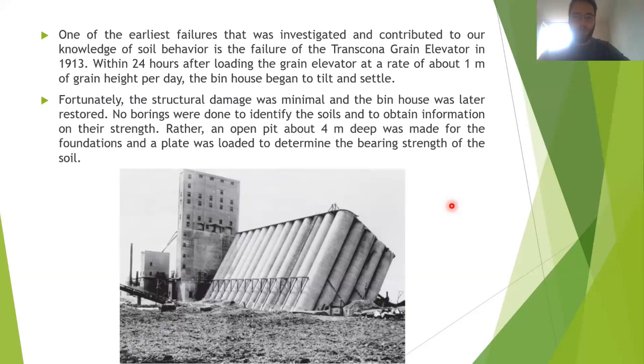So usually when you make designs for highways, for buildings, for anything, you design for the next 100 years or the next 50 years. In Europe, you usually design for the next 100 years. For underground mines, that's a bit less, around 20 or 30 years, because they're not entire structures. But yes, that's a really good question.